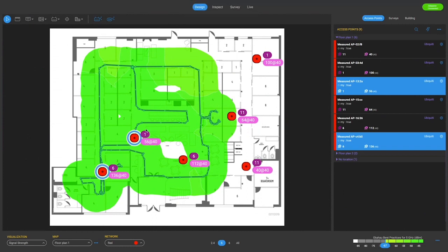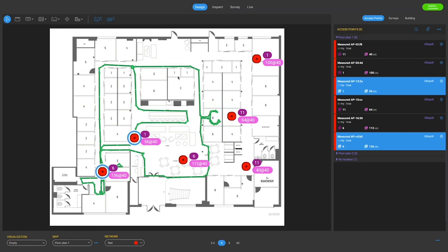So when you've done your designs, you initially place your walls, right? And you pick the drywall, for example, that's 3 dB. We may not know if that wall is actually 3 dB, right? Either your building has not been built yet, or you need to do a wall attenuation measurement. Well, the wall attenuation calibration feature will actually help measure that for you using survey data. And so what we're going to do here is, I think, Francois, you're going to draw in some walls and see if you're accurate with your attenuation prediction, what attenuation measurement you're picking.